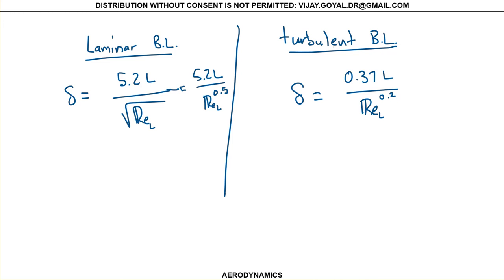These are approximations that typically happen in a typical aircraft. And this basically wraps up all our discussion of turbulent and laminar boundary layers. The only reason we have this discussion is to understand how the aerodynamic forces work. Again, I keep emphasizing, I want to make sure that my plane flies, right? In order for my plane to fly, I told you no air, no motion, no air, no lift, so therefore my plane doesn't fly. But at the same time, you're going to have a drag, and the drag is going to depend on how much viscosity is there. One of the drag terms, and drag has many terms, is the viscous drag. That one we cannot avoid.